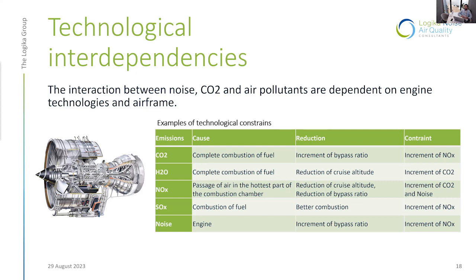At the same time, if you were trying to reduce the NOx, by, for example, reducing the cruise altitude or reducing the bypass ratio, so doing the opposite of what I just described for reducing the CO2, of course, you would have an increment of CO2 and at the same time an increment in noise, due to the reduction of the distance between source and receiver, because you would fly at a lower altitude, and at the same time, the way the engine works would generate more noise.